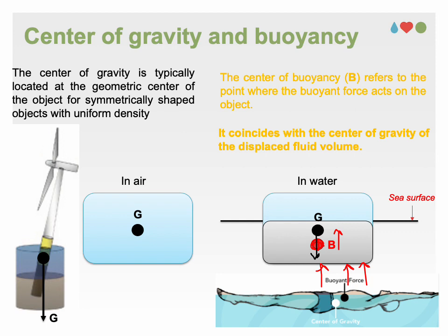The center of buoyancy is the center of displaced volume of water. For our floating cylinder, it's located at the geometrical center of the submerged part of the cylinder shown by the gray color here.